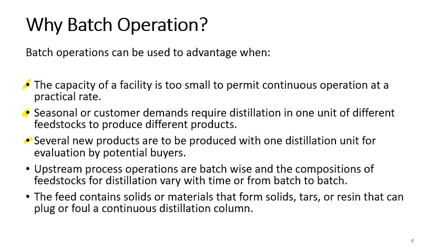And there are also other reasons: varying compositions of feedstock, varying composition of product, and also maybe the feed contains solids or materials that can plug or foul a continuous distillation column, because if you run it in batch, then it's easier to just stop the distillation process, take out the reboiler and clean up, and then replenish the reboiler with a new batch of feed.